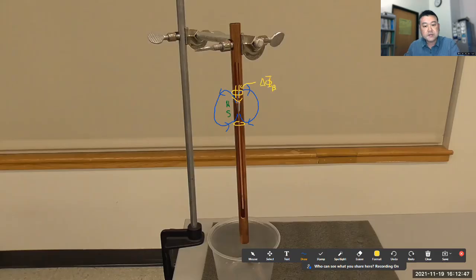And Faraday's law says that the line integral of electric field, or voltage, is associated with the rate of change of magnetic flux. So there's a voltage induced around this loop. And Lenz's law, which is referring to this minus sign here, says that you can figure out the direction of the electric field this way. If you imagine the current being produced by this induced voltage, then the direction of current is such that it opposes the direction of the original change in magnetic flux. So here, let me use one of my shortcut right-hand rules.